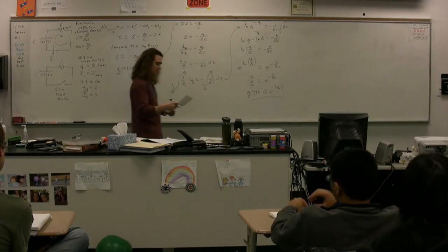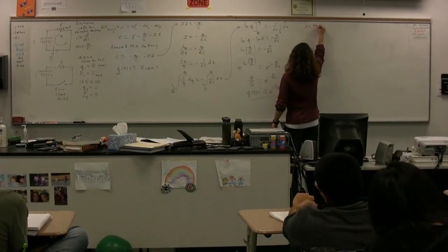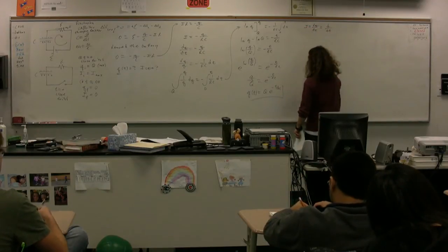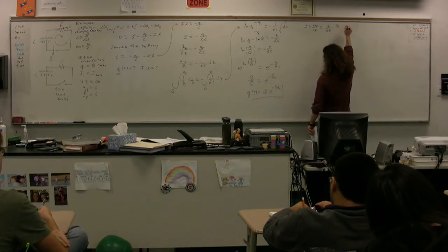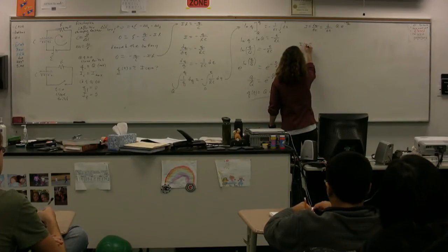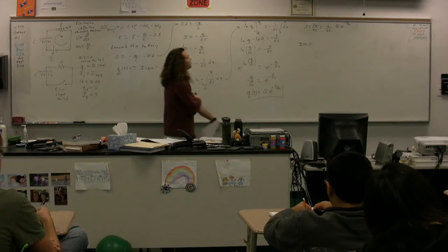We start with dq over dt again. So we have current is equal to the derivative of charge as a function of time. True. And we have the equation for charge. It's equal to big Q e to the negative t over RC. Current as a function of time then is going to be equal to, please take the derivative, Nick.